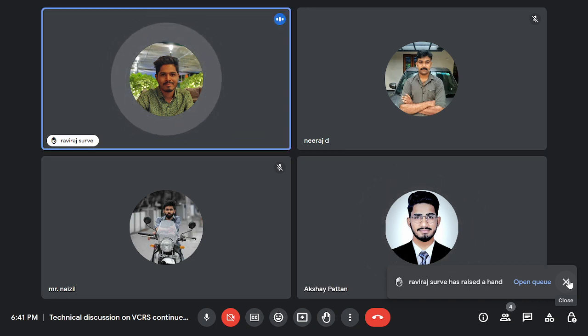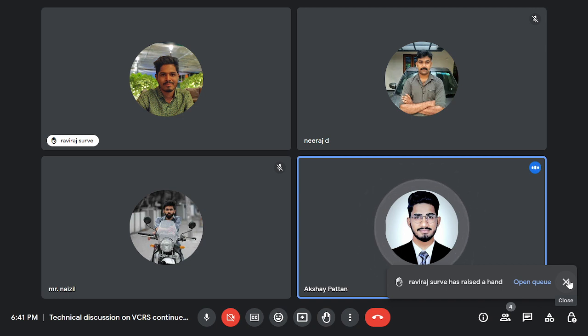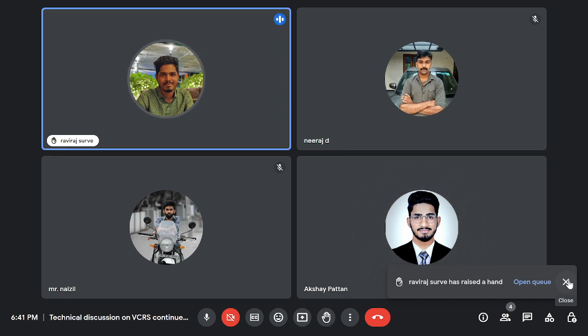I think maintaining different temperatures in a refrigerator can be achieved by using a single compressor. This concept is called dual cooling. Only a single compressor is used. How do you achieve the different temperatures? In this system, the refrigerant is separated into two circuits, each circuit with its own evaporator and temperature controller. One circuit cools the refrigerator compartment, while the other cools the freezer compartment.